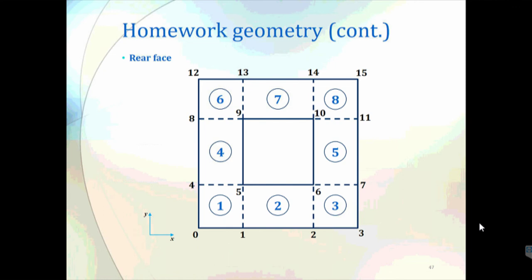So these are all the real faces for the blocks, which I have numbered. You can see the numbers over here: 0, 1, 2, 3, 4, 5, 6, 7, 8, 9 until 15. So there are 16 vertices on the rear block. Why do we need numbering? Because later on, when we are defining the block, we have to use the numbering of the vertices.